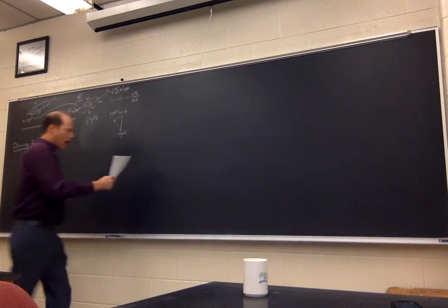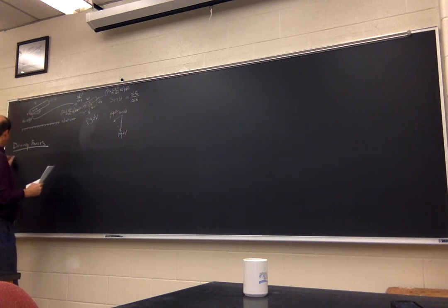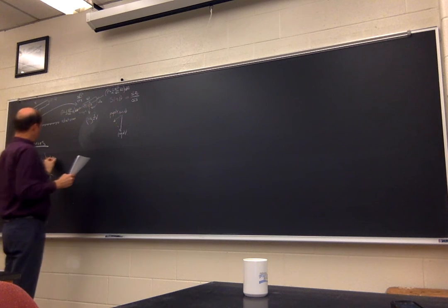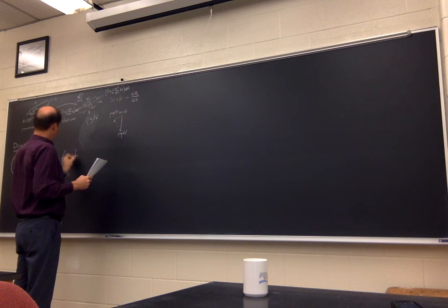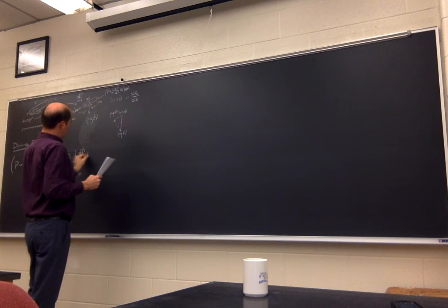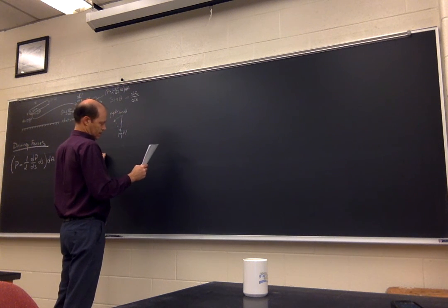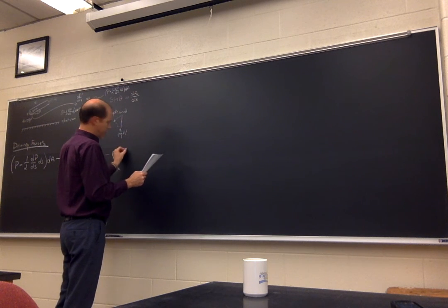So on the driving force side, we can basically add up all the parts that we wrote out here, which is (P minus 1/2 dP/ds ds) dA minus (P plus 1/2 dP/ds ds) dA minus rho g dV.